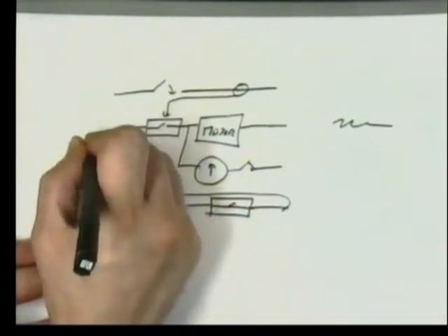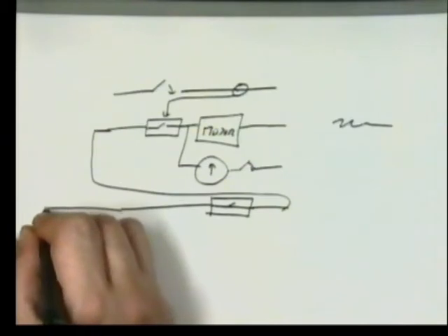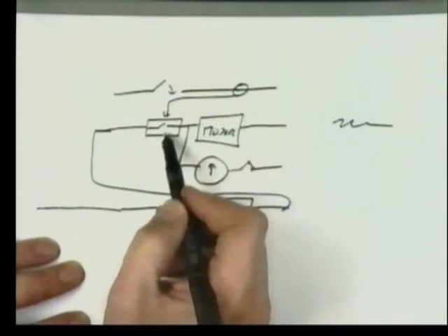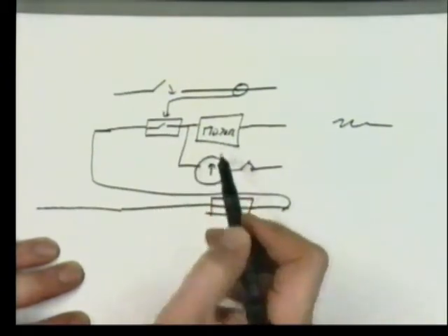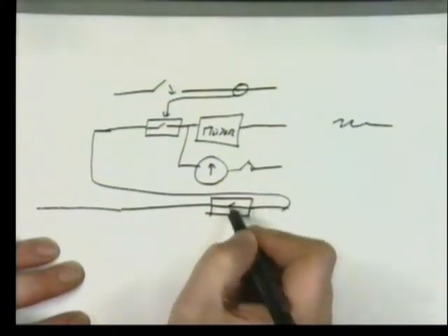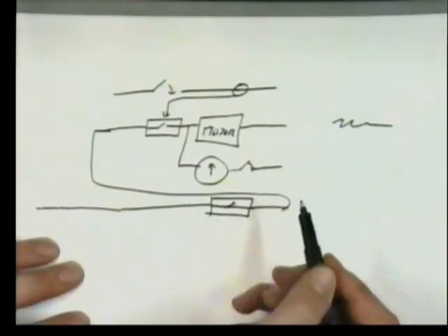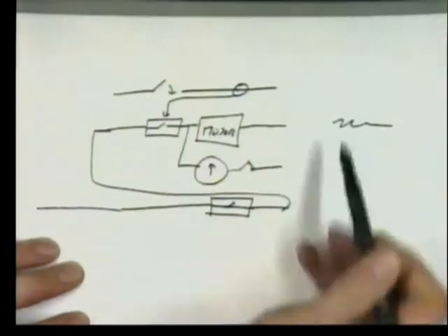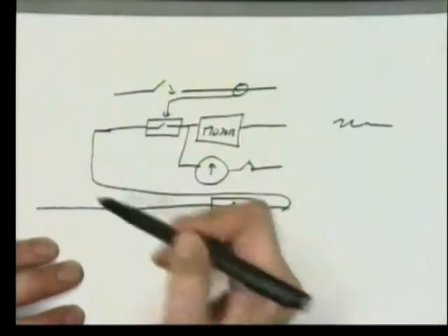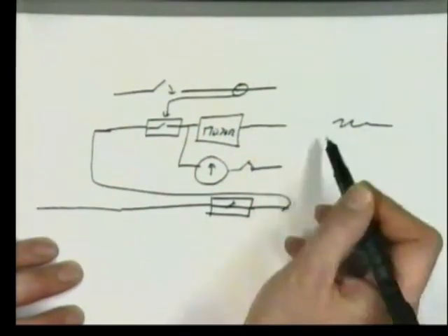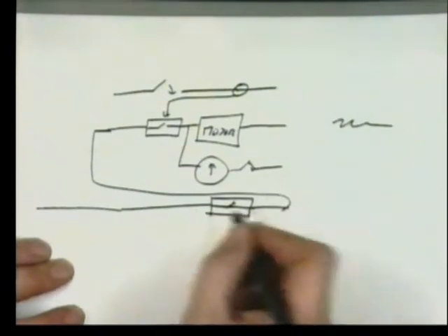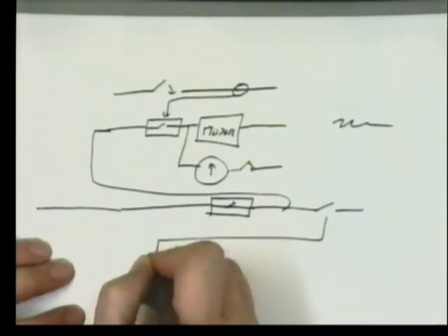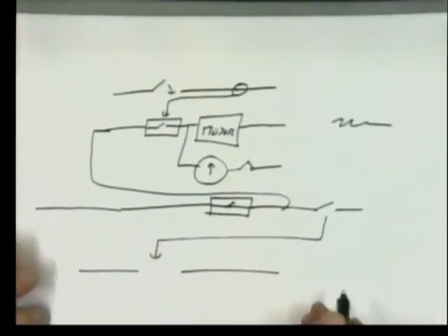Now if that was put into this circuit here, hopefully you'll see this switch will turn on that relay, will turn on that power, turns on that motor, and eventually the timer times out and that switch is open and turns the motor off. So what we have by using a motor, a timer and two relays, it's not a perfect circuit, I'm trying to give you the idea, we have the ability to time how long a motor comes on. Now, the next thing we could do is that we could then have this close another relay and start off some other process further down.